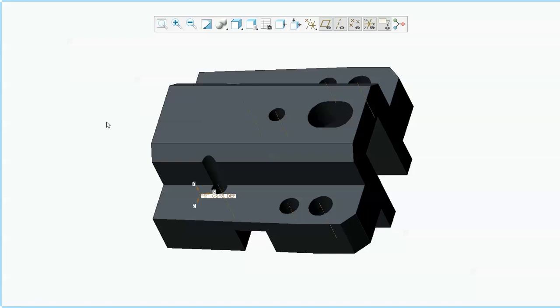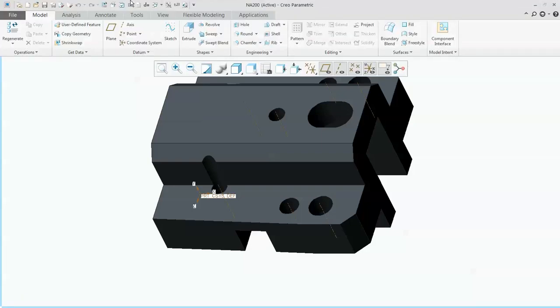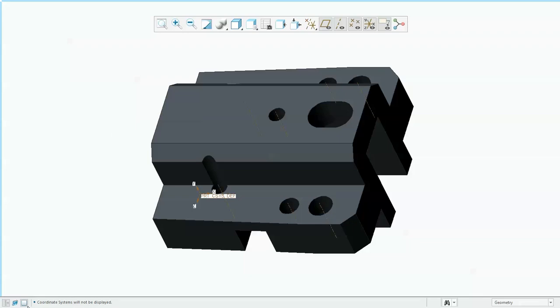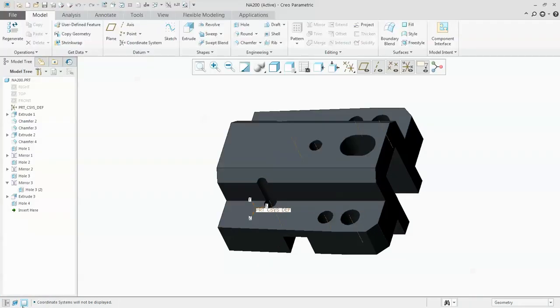And let's now bring our cursor up to the upper middle area of the interface there. You can see the ribbon does expand down. I get all this while I'm in full screen mode. It does allow me to still work as I traditionally would, but without having the hindrance of those other sections of the interface. I can exit out of full screen mode by either selecting the same tool, the button or the F11 key again, which will bring you back into the traditional visual representation of the interface.